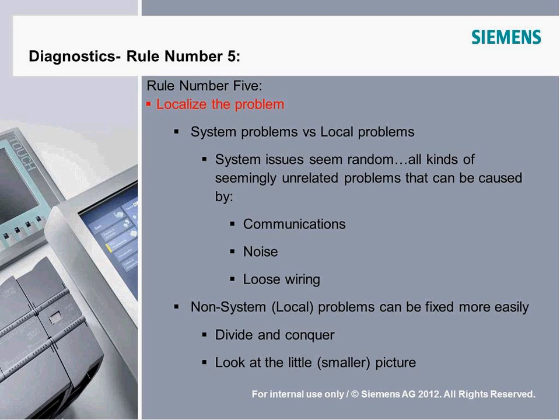Wiring is a major one. I'd say it's certainly more than half of all problems have to do with wiring. Where the rubber meets the road, PLCs and so forth, and I/O cards are typically in a nice environment inside their cabinets. And then if we go out into the real world, out on the machine, we have all kinds of flexibility issues with wiring and flipping, smashing stuff, and who knows what else. But loose wiring can be a very difficult troubleshooting exercise, and we'll talk a little bit about intermittence.